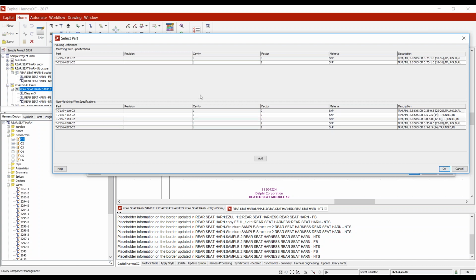So when validating your customer's choices, you'll let the system auto-select the terminals based on your manufacturing processes. For example, single loose piece terminals versus the reel terminals. If you have an applicator, you would give the reel terminal a higher factor.